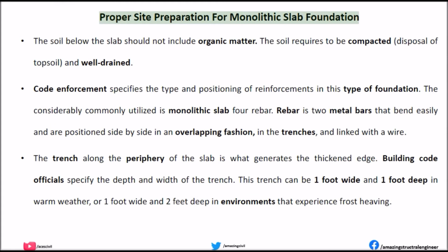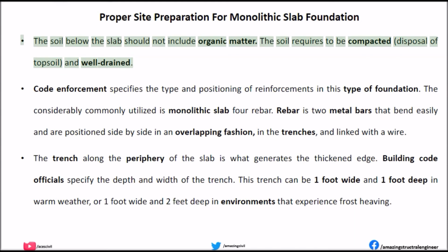Proper site preparation for monolithic slab foundation. The soil below the slab should not include organic matter. The soil requires to be compacted, free of topsoil, and well drained.